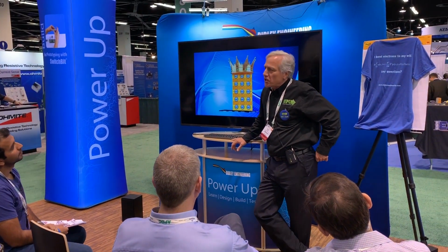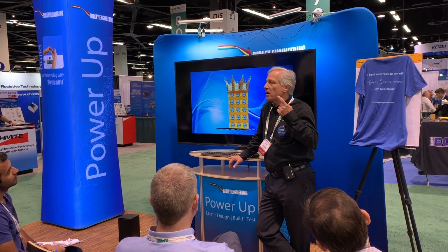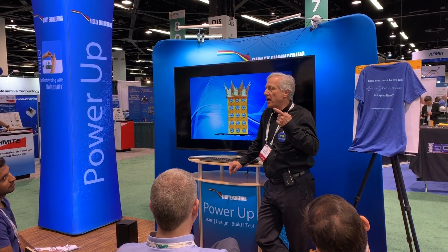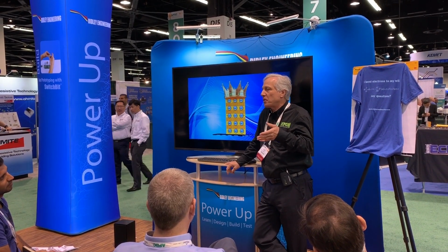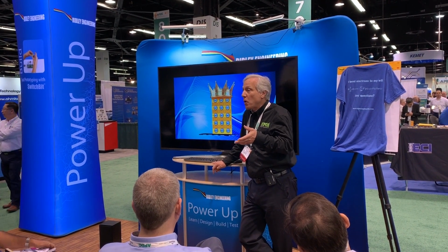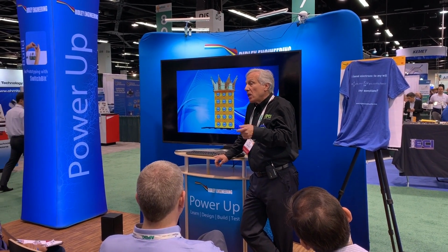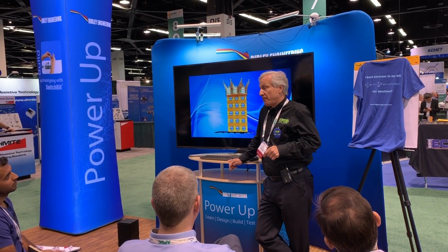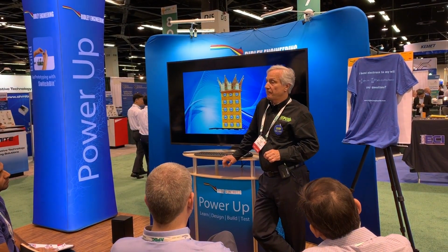Look, you can push as much current as you want. It just depends on how big you make your chip. I don't remember what our 350 volt chip's current rating is, but I do remember that our 30 volt chip has a pulse current rating of 590 amps, and it's 12 square millimeters. It's just a whole lot of current that you can run through it. And our LiDAR customers use that stuff. LiDAR runs right up against our pulse current limits.